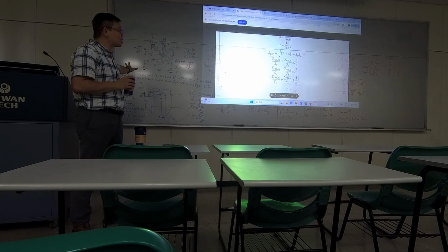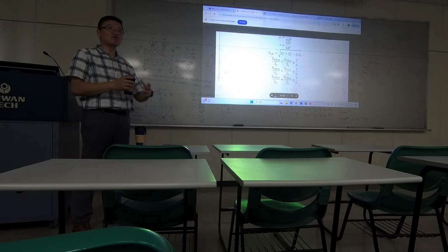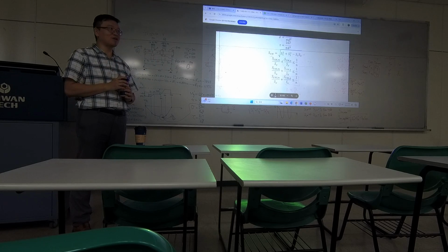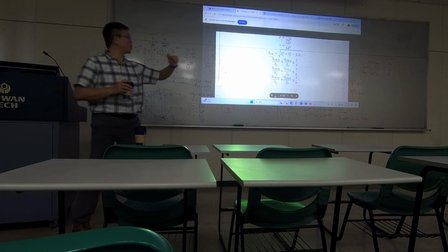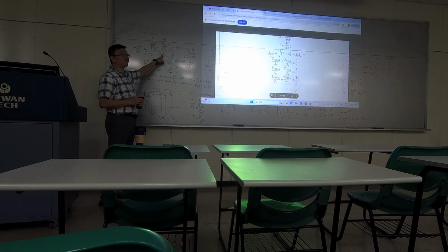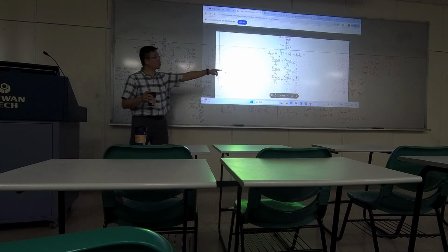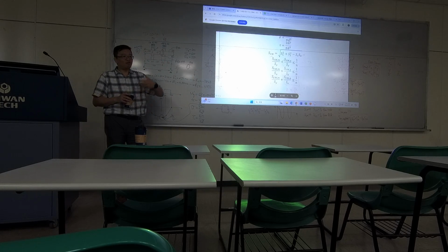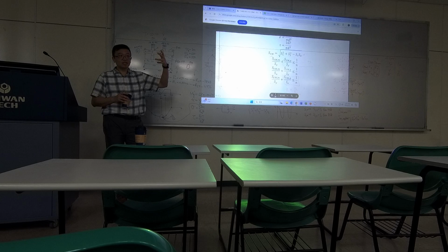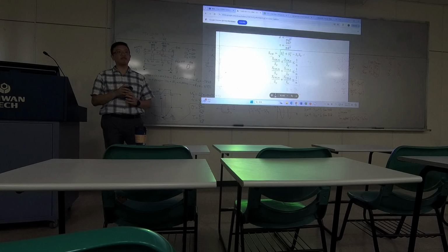But this is basically how you can at least get some solution. It's a pretty good estimation, and I would say whatever I'm doing here should be quite conservative, because right at the 304 position, the stress concentration level should be slightly lower than at 300. But we still use the same level of K. So we are overestimating the stress. That means we are playing conservative. It's okay to play conservative.